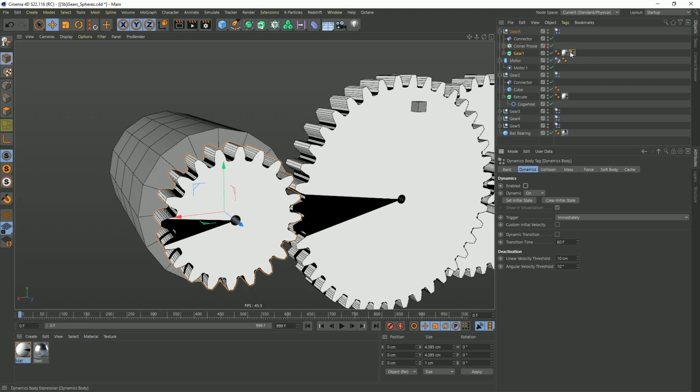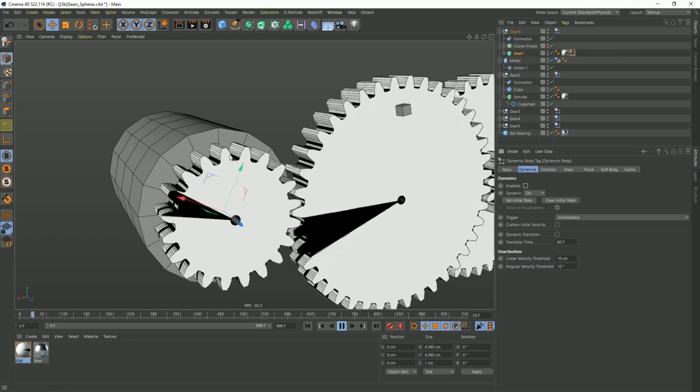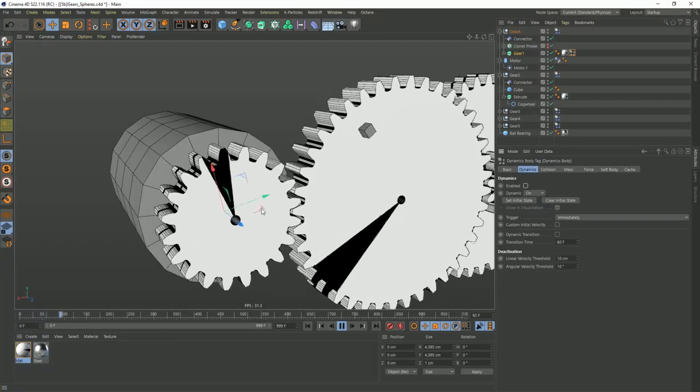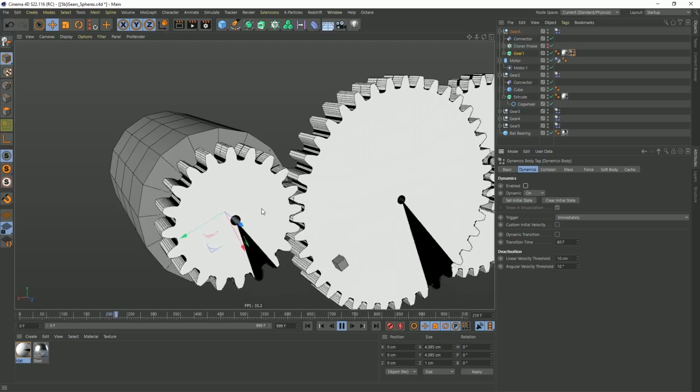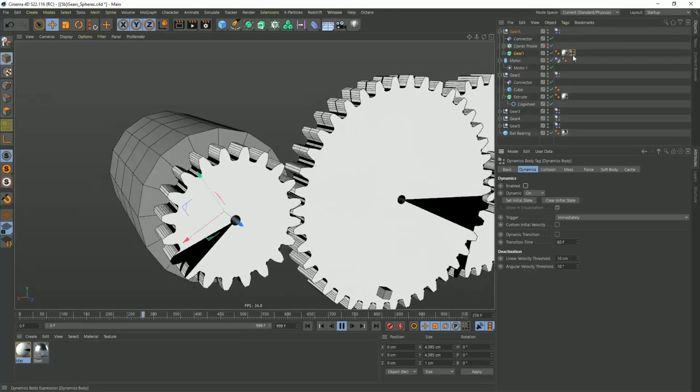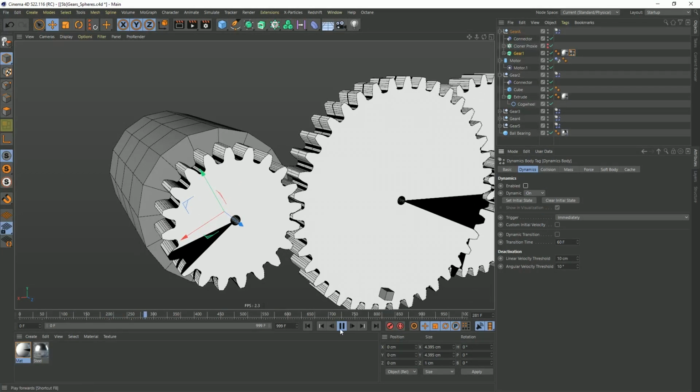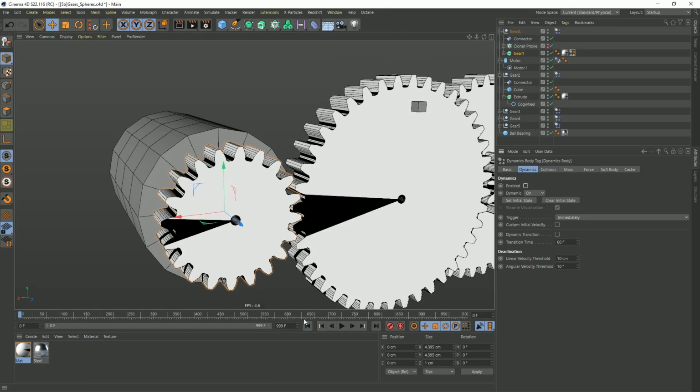But then it's going to bump into this dynamics tag and be like, oh, whoops, sorry, ignore you, don't do anything with that. So what's cool is this is a child of something that's a compound collision shape, but it itself won't be calculated. So all that calculation time is gone, but we can visually see it doing everything that we want it to. So there we go. That is a really great, quick combination of those just by using a second dynamics tag that is going to ignore those. So that is working quite nicely.